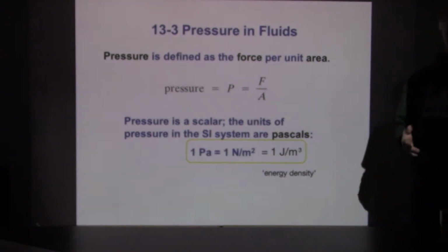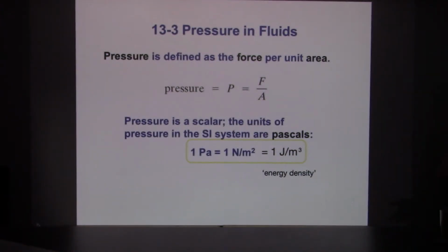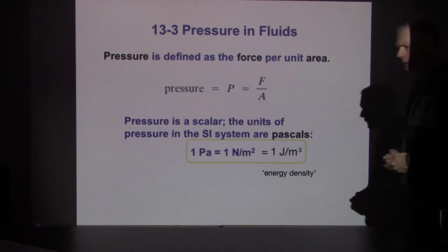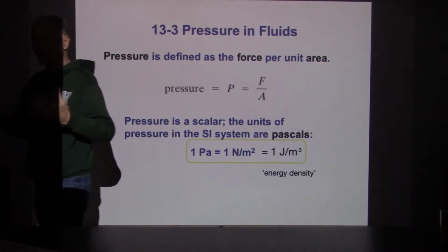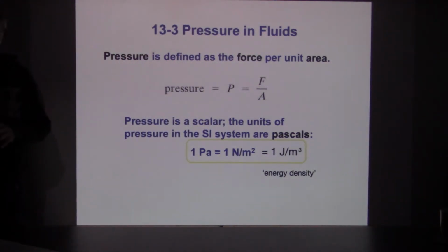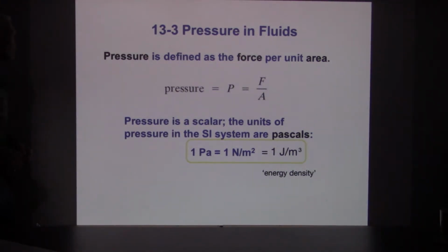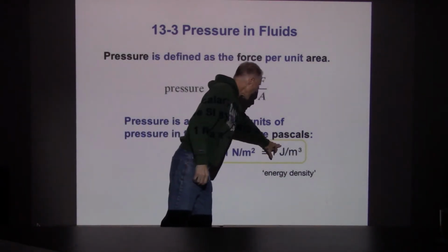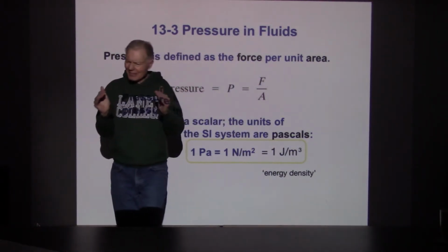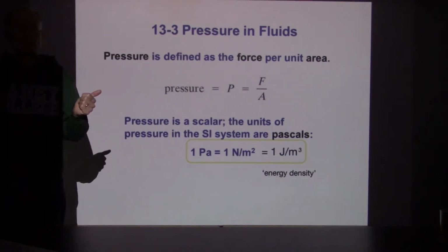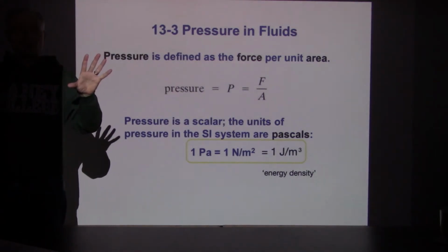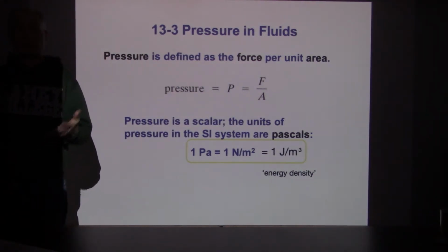So what happens is, if we compress the fluid, if we put it under higher pressure, actually it's not very compressible. By compress here, I'm thinking if we place a compressive stress on the fluid, volume doesn't change much, but the pressure will. So the pressure is going to go up when we attempt to compress this fluid. And when we put it under higher pressure, it compresses a little bit, and that stores energy.